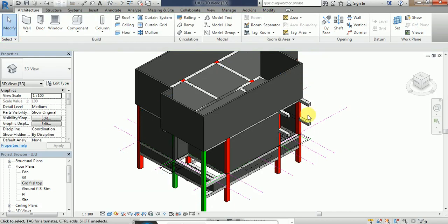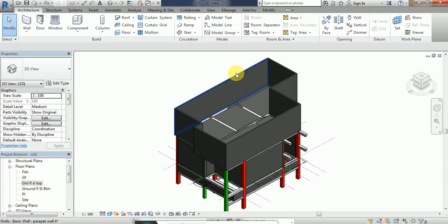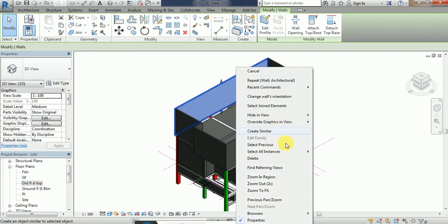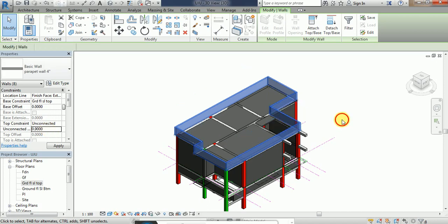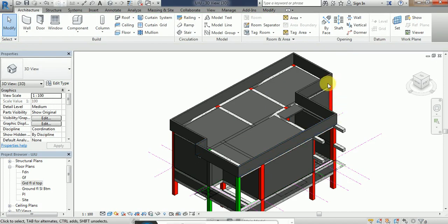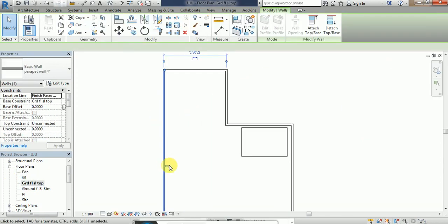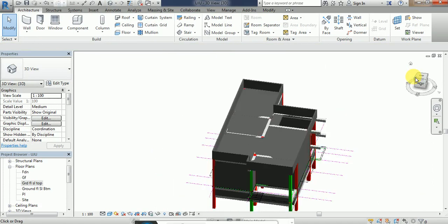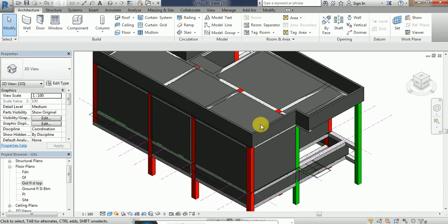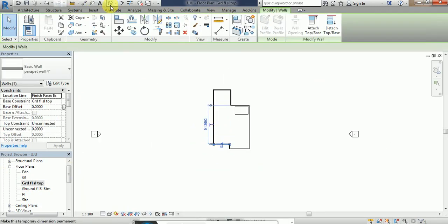you can see in the 3D wall, but I have made a mistake. For that particular wall, select all constant instances; it should be with the height 3 meter, which you can change afterwards also. That will be 0.9. Okay, but you can see this wall is on the outer side. So again I will have to select this. I think now the wall is placed properly, but in some places it's not. So there is one mistake. You will have to use the space bar again to make it sit in the proper position.